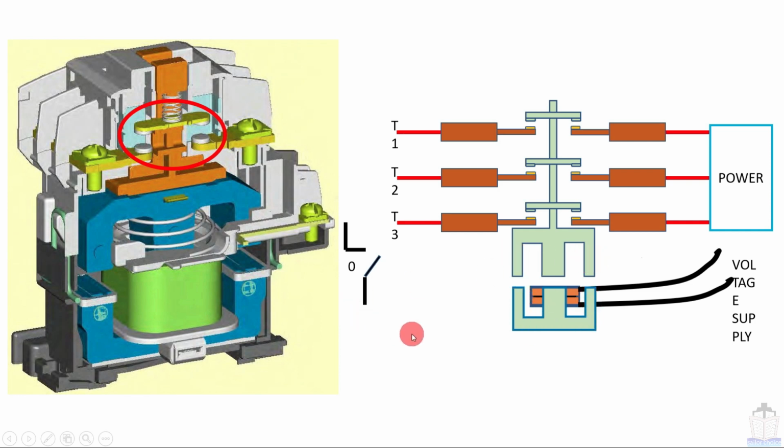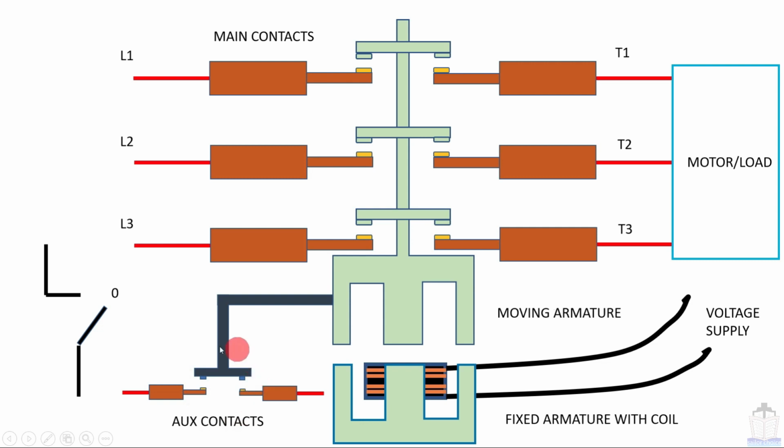Okay. So now we are taking you to the animation part of this magnetic contactor so that you can understand how an auxiliary blower or HPS pump start-stop signal is generated, transmitted to ECS, and we get information over MOP for the same. Here this represents the auxiliary contacts that I have already shown you.